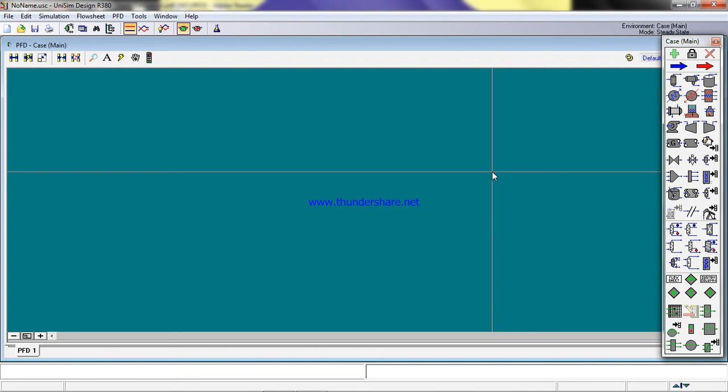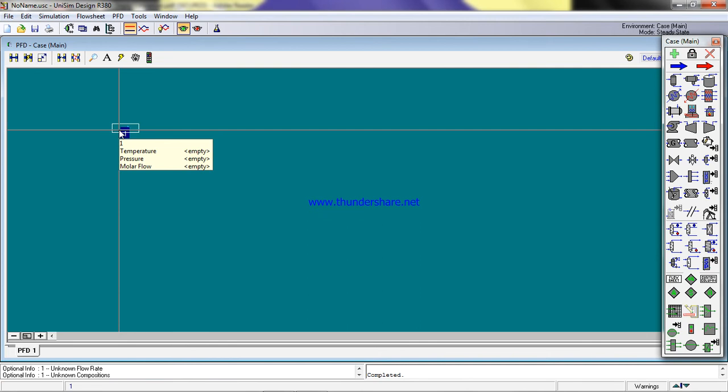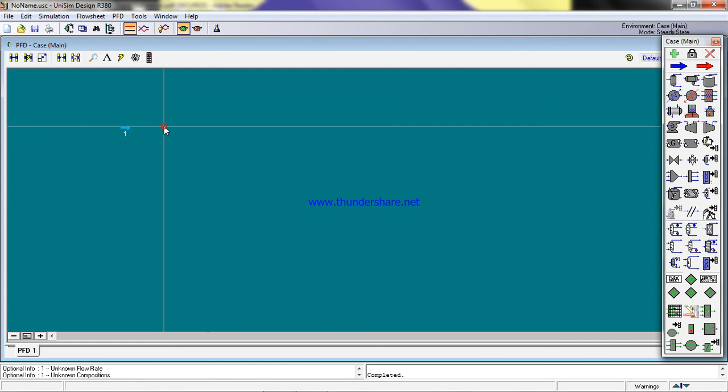Okay, you do your connection, and you connect all your equipment. If it's a full plant, you line up your pumps, your heat exchangers, your separators, your mixers, and everything that you would think of, you find them here. Okay, the stream. Now let's see, we pick material stream. We want to see the materials. We want to fit in those two reactants.